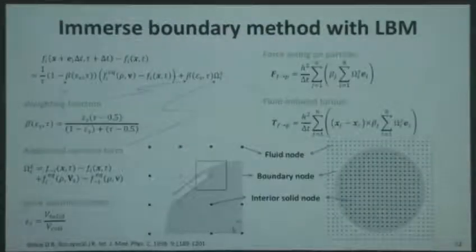So with all this, we still need the coupling between the two phases. So in this case, we use the immersed boundary method. So we are using the classical force-induced method. So the force acting on the particles and the torque on the particles are all solved for each surface lattices. And the source term is added to the momentum equation in the fluid flow.